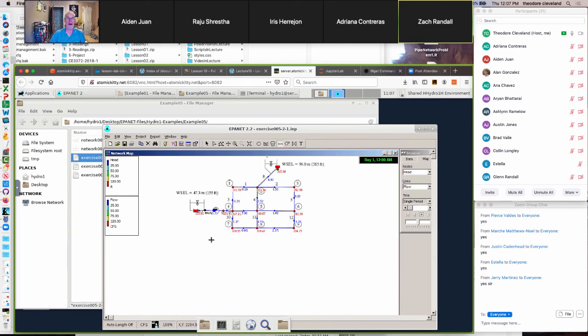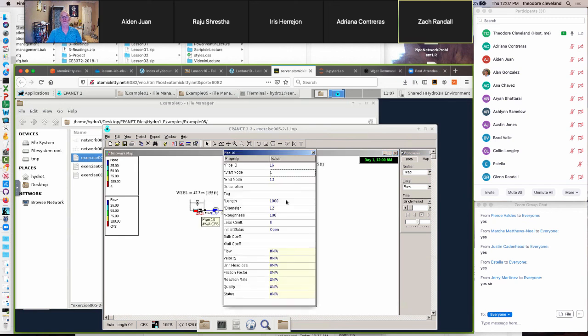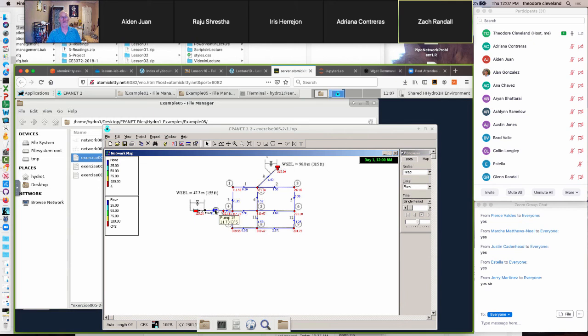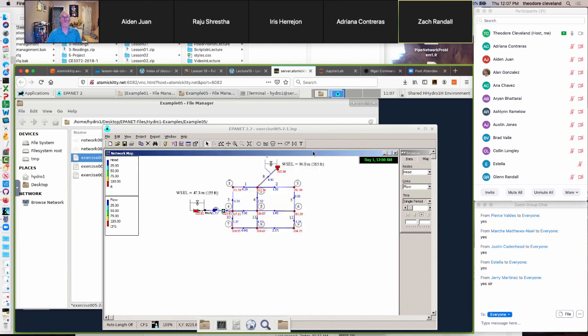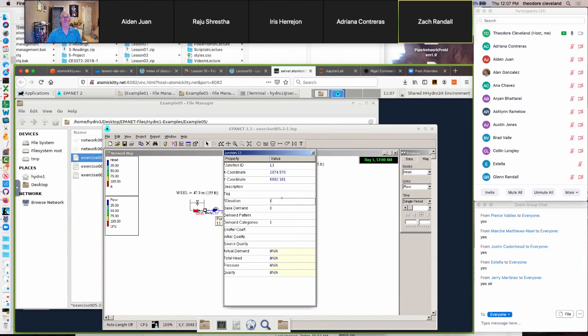And then we'll go back and adjust elevations. And actually probably pipe properties. So we'll make this a pretty big pipe. Get my roughness down to 1, so that should be consistent with the rest of the network. Our pump is fine, and now we have to decide what elevation we want things. We certainly don't want it at 0 because that's a node that's down in a hole. I'm picking 155. That's the elevation of junction 5. And we will keep the pump at the same elevation.